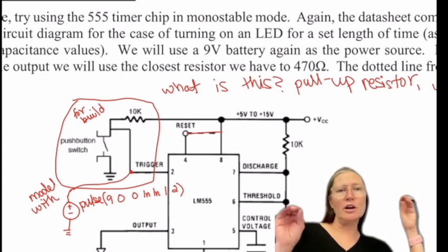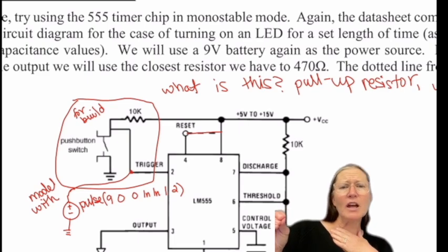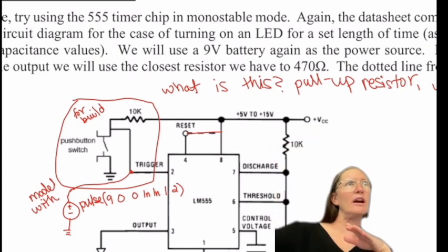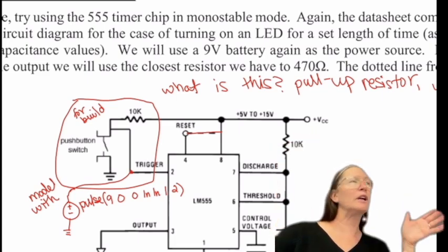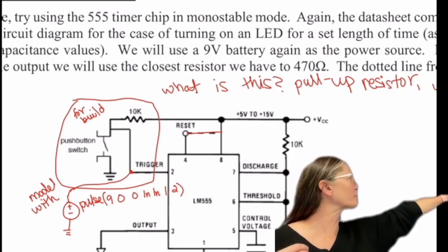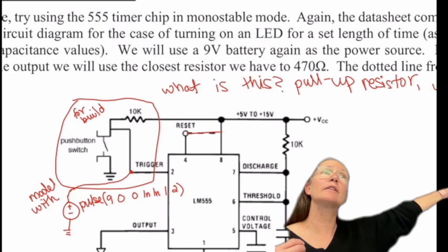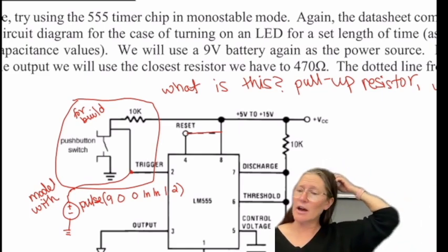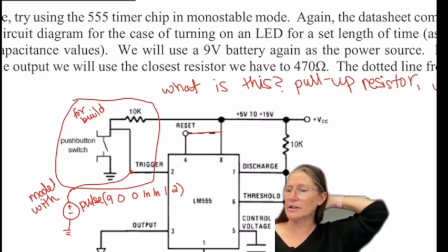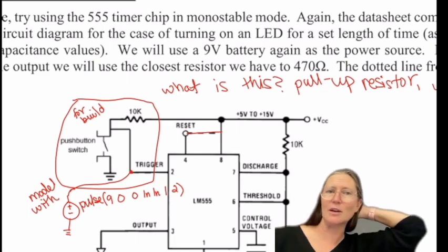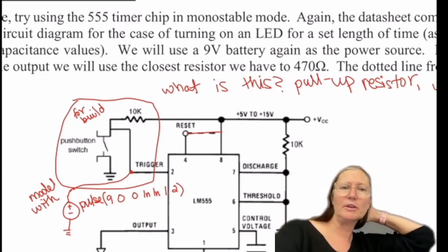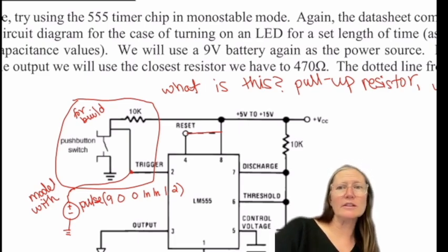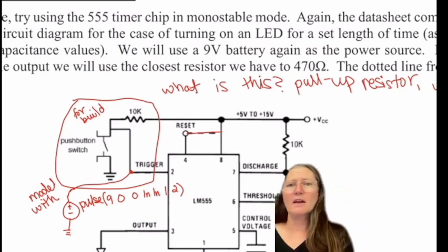It's the voltage on, the voltage off, and then the time delay, and then how much time it takes to rise, to fall, and then the full length of time you want your whole pulse to be in, the period, is the last value in there. Okay, so that should work to get that pulse to trigger it instead of putting the push button and the 10K, which is hard to model in PSpice or LT Spice. So it should look like this for your monostable.